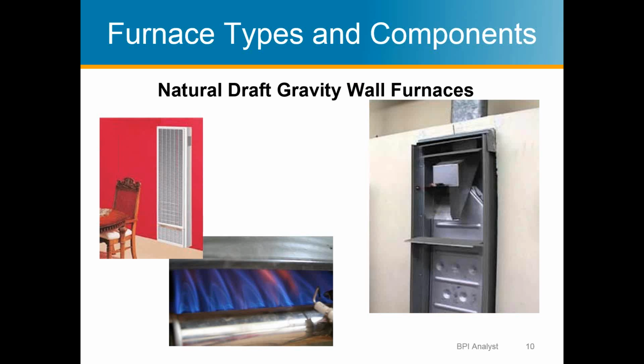I grew up in Indiana, and I never saw one of these till I moved here. But if you pay attention to the Hollywood movies, you'll see these in the backgrounds, I later realized. But that's what it looks like. The picture here on the right is showing it without the cover on. It's natural draft, which means it takes outside air and mixes with the exhaust gases, and that's this box right here. And then it exhausts out the vent.